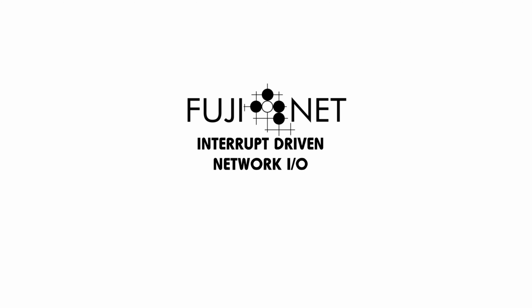What can happen instead is the ESP can indicate that something needs to be paid attention to by lowering the interrupt line for just a moment, just long enough for the Atari to notice it, and the interrupt routine on the Atari can then issue a status request to get how many bytes are waiting or if the connection status has changed, etc., and go from there. This greatly increases the efficiency of network I/O, as we'll soon see here.